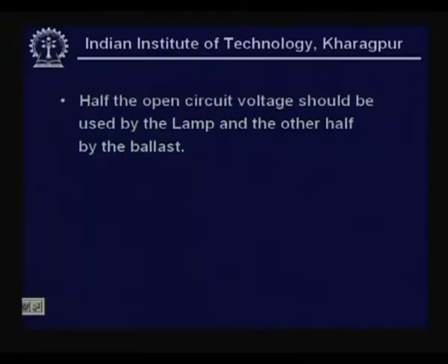Now the issue is, we have already said, although discharge lamps radiate mostly by arc, they have two electrodes at either end, which, depending on the cycle of the AC sine wave, each act as a cathode, and hence each cathode is in turn heated by a filament which is similar to your incandescent lamp.